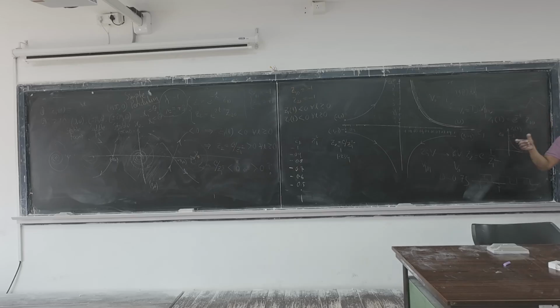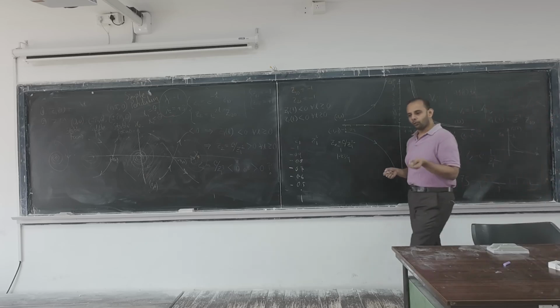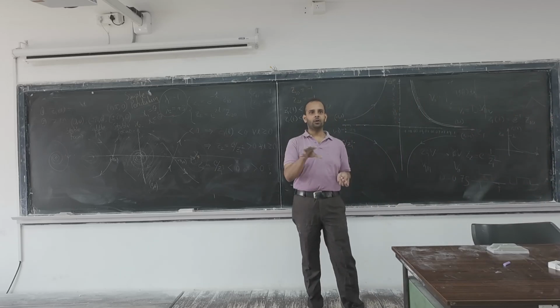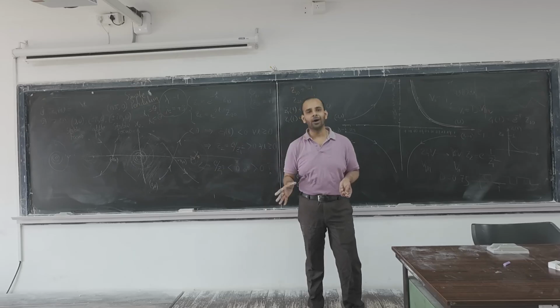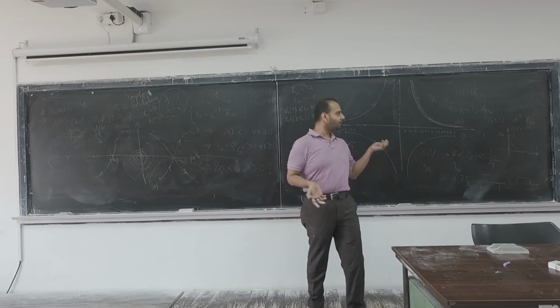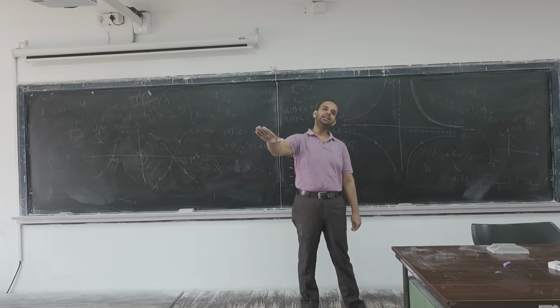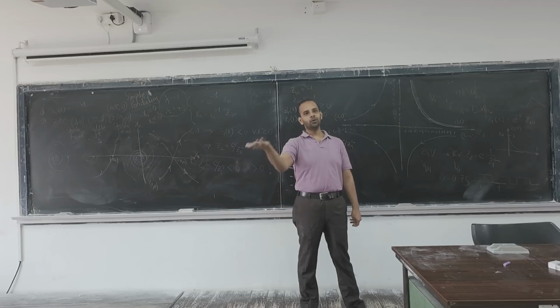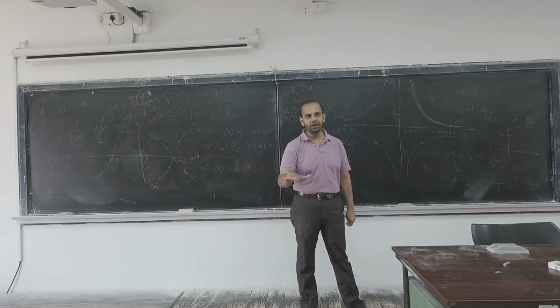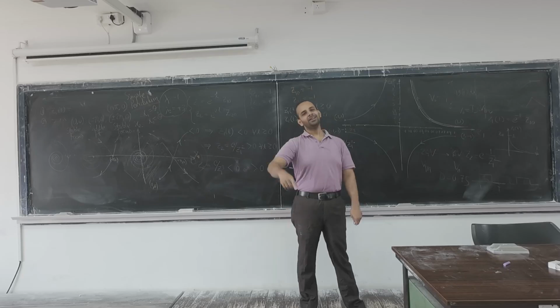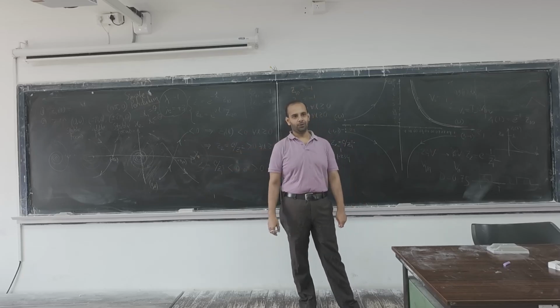That is where we create this type of situation where we force the system to switch from one equilibrium point to the other, or rather we should say operating point, because this is forced. So we force the system to change its operating point, and that too for a purpose. It is not that we do it without any reason. Suppose it is T on continuously, then what will happen? In the output you will get 24 volt, no reduction. Or if it is switched off, then in the output you will get 0 volt.